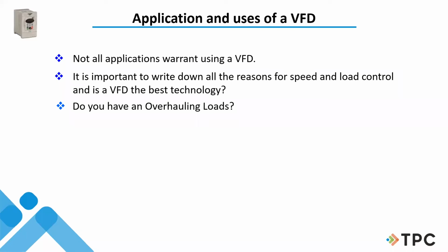So I need to know if I have an overhauling load, and a lot of times just getting a bigger drive, it doesn't necessarily mean I have to change the motor, but just getting a drive that can handle more current will help me get around some of these problems. If you've programmed it so that it slows things down gradually, and you can get away from that overhauling load, great. But if it's too much, then you probably need to get a bigger drive.